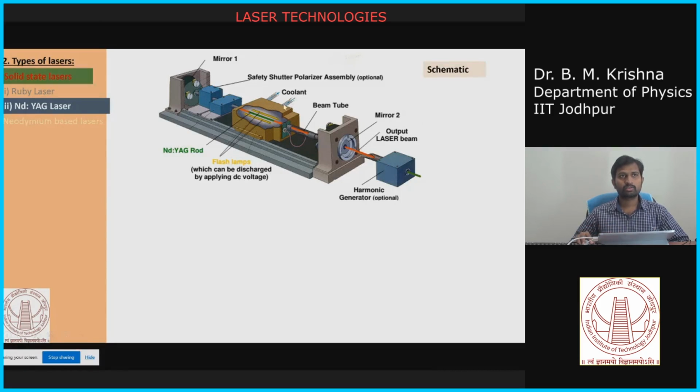And you see there are two other tubes here. These are water cooled. As you know, of the flash lamp energy, only 1 to 2% is utilized for lasing. The remaining energy is wasted in the form of heat, which may give a lot of heat to your lasing medium, and then you will destroy the lasing action. To avoid that, we have to cool your laser rod as well as the assembly. That is where these lasers are generally cooled with water chillers. The chiller continuously flows water, and it has a refrigerating unit, so that it always cools down by circulating the water along this chamber.